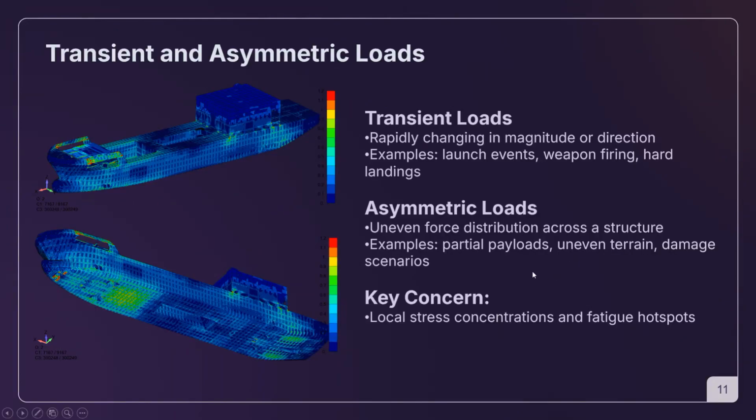And here again, combination factors may vary, which will also lead to some local stress concentration. And as you know, these structures used for defense and military should have a much longer life cycle than the average structure, and also stress differences, delta stresses taken for fatigue calculations, will be much greater in these cases. So this also should be taken into account, not only the blast or loads which can occur, but also these long-term loads which act on the structure for a whole period of working time.